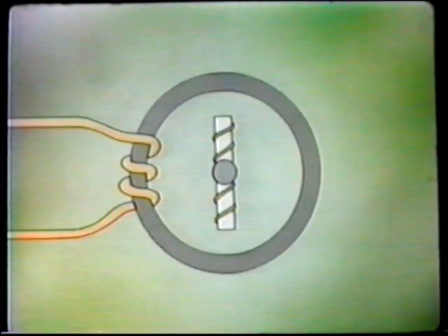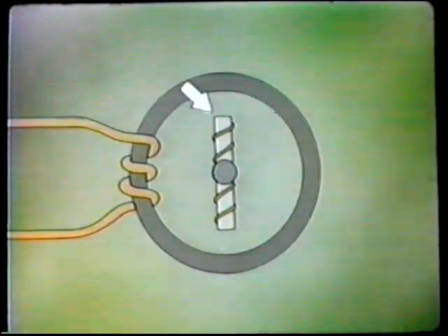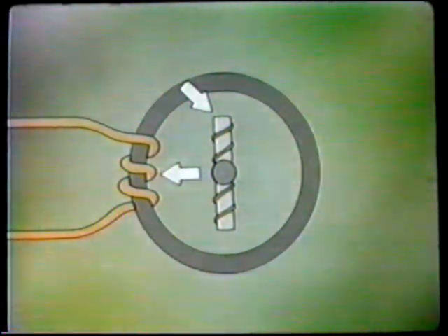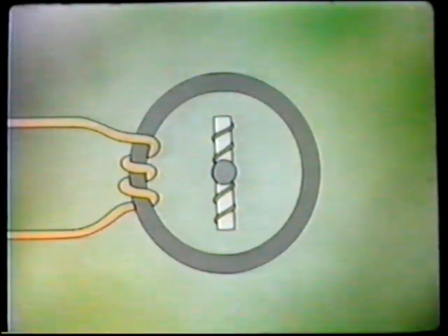Here's a simplified version of an AC generator. Its important parts are a rotor, here, and a stator, shown here. In this example, the rotor's an electromagnet that's connected to a DC power source. The stator's represented by a coil of wire wound on a steel core. Generators in your plant may have many coils of wire, but we'll show only one coil here.